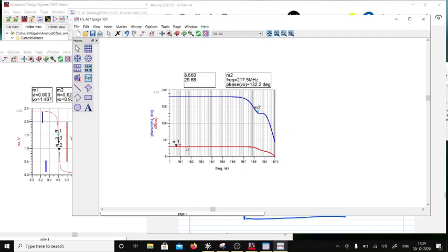So there was a fall off at 20 dB per decade, and as soon as you get a 0, you will be at 40 dB per decade, and then there will be another corner coming here. So it will give you an additional 90, so 90 roll off, flat, or plus 90, right? And then another roll off.